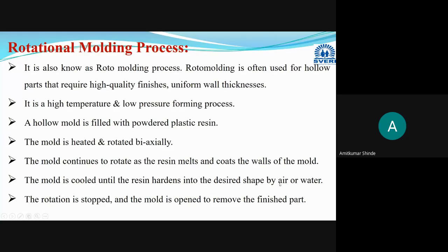Cooling is done by air or water, but largely we go for air cooling only, because water cooling may cause distortion and affect the final dimensions. Then rotation is stopped, the mold is opened, and the final finished part is obtained. This is the rotational molding process.